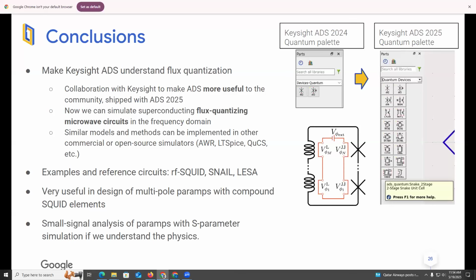Our readout band is limited to something between 500 megahertz to a gigahertz, not necessarily because of our amplifiers, but because of other constraints as well. So if we have a TWPA that has 4 gigahertz of bandwidth, it's nice, but most of that bandwidth is not utilized. So we're paying a lot for that bandwidth. We're paying a much higher complexity. We need like 3,000 junctions, a bigger chip. We're paying a little bit in performance, although that is being worked on currently and being solved by a number of groups.